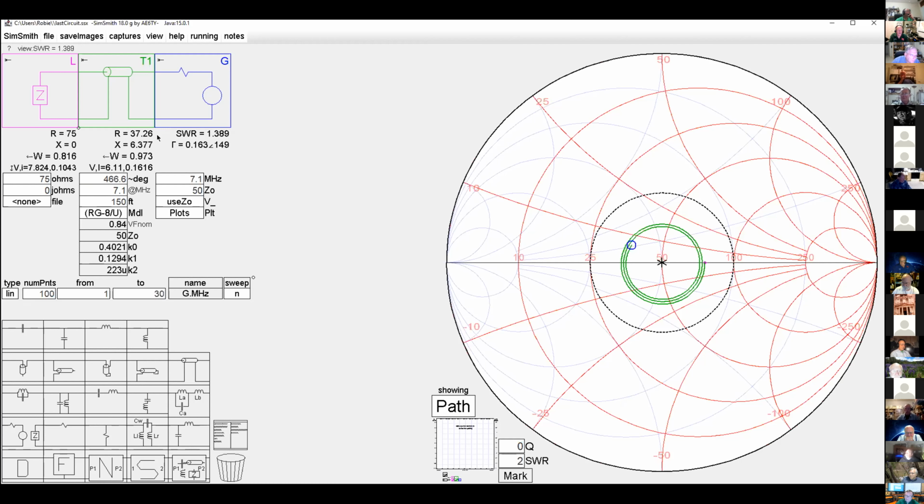That's right. Okay. Hey, Robbie. Go ahead, Rick, W5RH. Hey, if you measure your SWR in your shack, so to speak, at the generator, but with this tool, you can see what the SWR actually is at the antenna. That's right. It changes along the line, but you can say, oh, I've got 1.5 to 1 here in the shack, but using SimSmith or the Smith chart, you can say, oh, it really is 2.5 to 1 at the antenna. So yeah, that's the benefit of this tool.